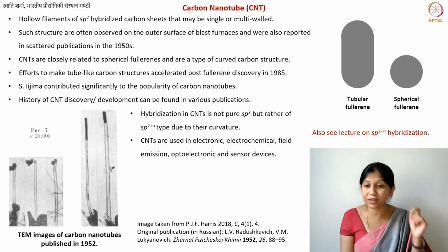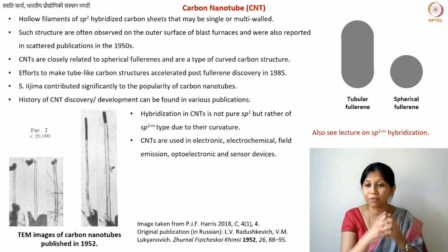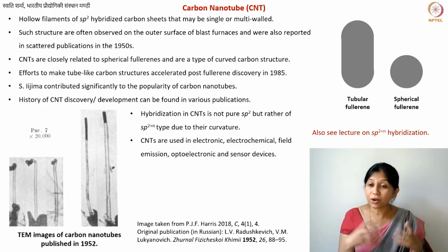There is a higher probability of containing defects. So defects and voids, these are your weak links. And those defects can come all the way from the polymer, in the beginning itself, if you had some lump of polymer or something like that. So that is the reason, that is where your fibers can break.